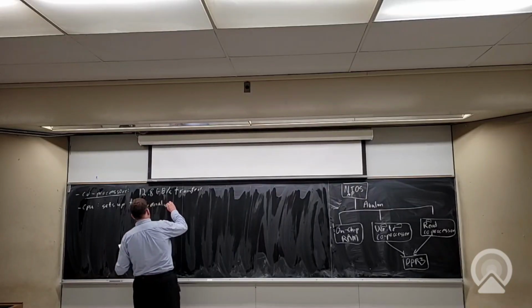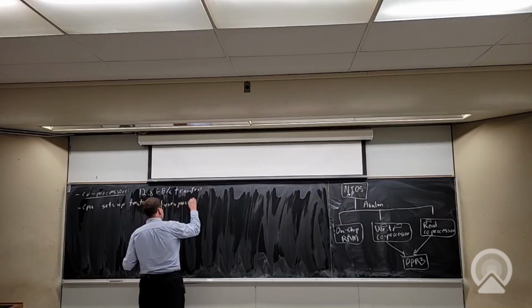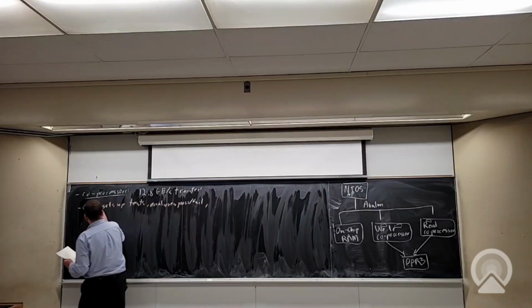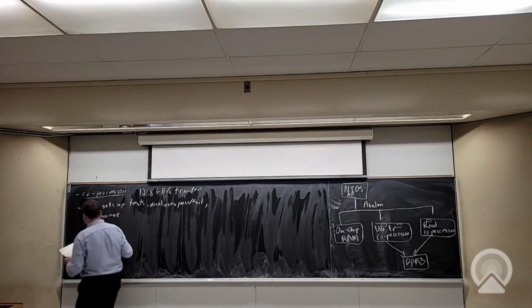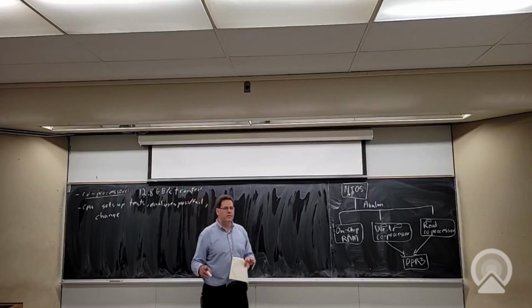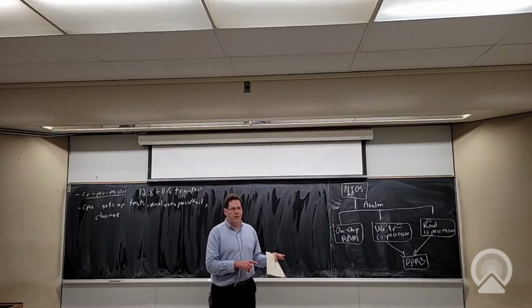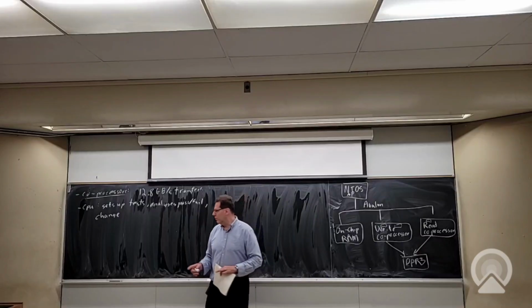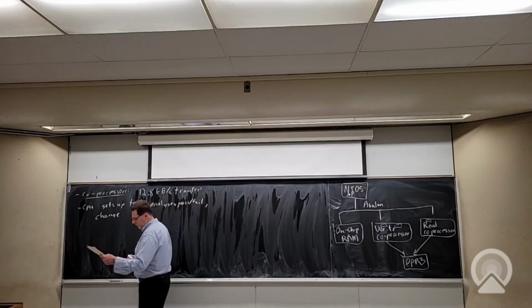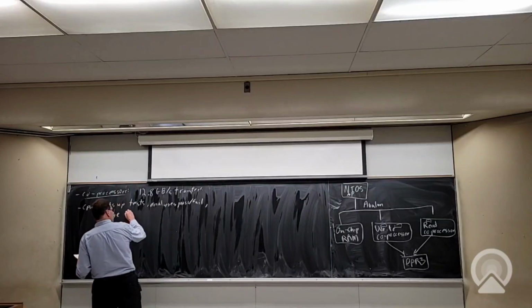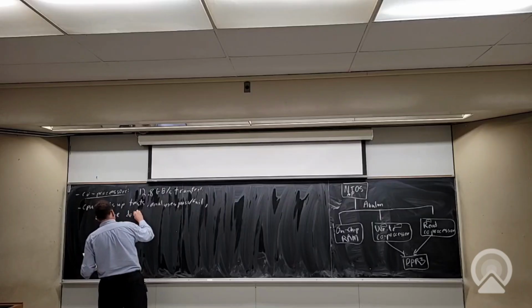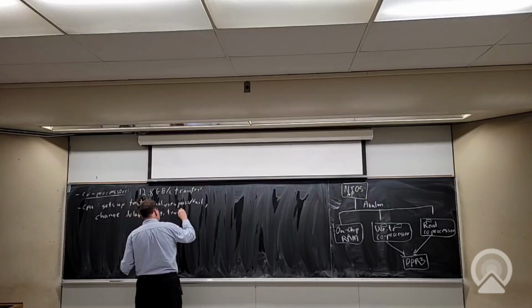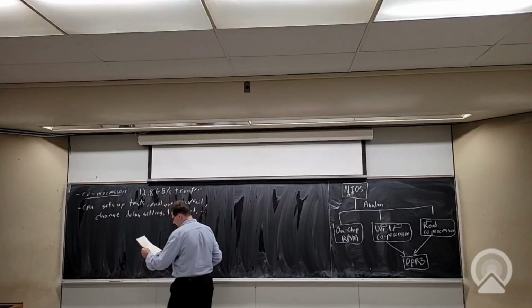So it analyzes pass-fail by looking at the data that came back. It can change the configuration. So it basically can write to registers to say, adjust the delay of this signal by this much, adjust the signal of that delay by that much, change the PLL settings. That can actually start moving around some clocks that also affect where these strobes are, etc. So change the delay settings, try the next thing, etc. Okay, so it's pretty complicated.